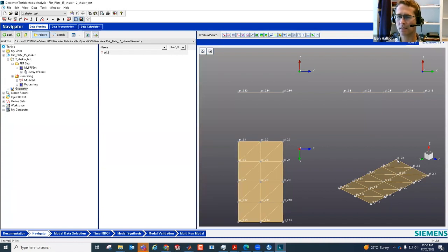In a modal impact exercise, you'll start impacting the structure at point 1, go to point 2, go to point 3, and then it's more convenient to go here to point 4 rather than to have to go back across the structure to point 4, 5, 6. It doesn't matter at all.